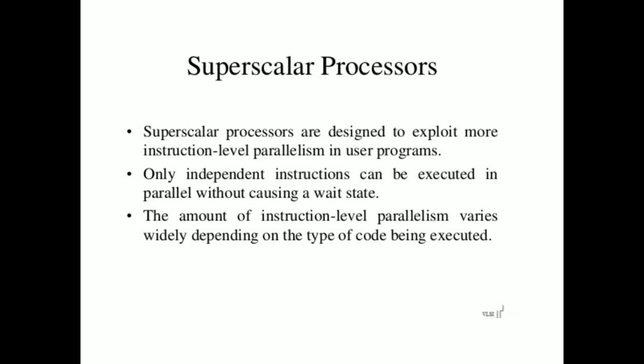A superscalar processor executes multiple independent instructions in parallel. Common instructions like arithmetic, load or store, etc. can be initiated simultaneously and executed independently. This is more commonly used in RISC.